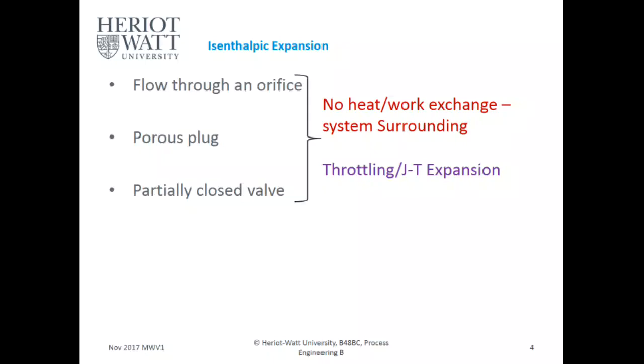So you have the gas. Imagine the gas going through a pipe, and then there is a kink in that pipe, so it gets throttled, and then expands again. If all of you try to walk out of that door and there's a fire alarm, first you'll run towards it, then you'll slow down, and then you'll speed up again as soon as you come out. Now, that speeding up affects the temperature of real gases.